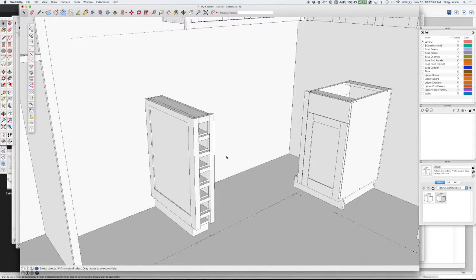However, not completely to my liking because I don't really like these mid rails here. And also, I need a lower rail on here for the face frame. See, in the rest of the kitchen, I don't use a lower face frame rail, but I do make the bottom rail on the doors a little heavier at 3 1/4. So what I'd really like here is a lower face frame rail at 3 1/4 to sort of mimic what's going on in the rest of the kitchen and get rid of these mid rails.